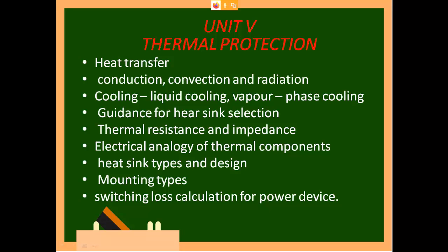Usually it is so in conductors, whereas when you take a semiconductor, it has its own resistance, so it will try to offer resistance to the flow of electrons. This resistance will be converted in the form of heat. Electron energy will be converted into heat energy. So you have to remove this heat energy from the device, otherwise it leads to a thermal runaway problem, and thermal runaway is nothing but a constant increase in temperature in semiconductors, thereby the entire device fails. So that is what we will see in unit number 5.